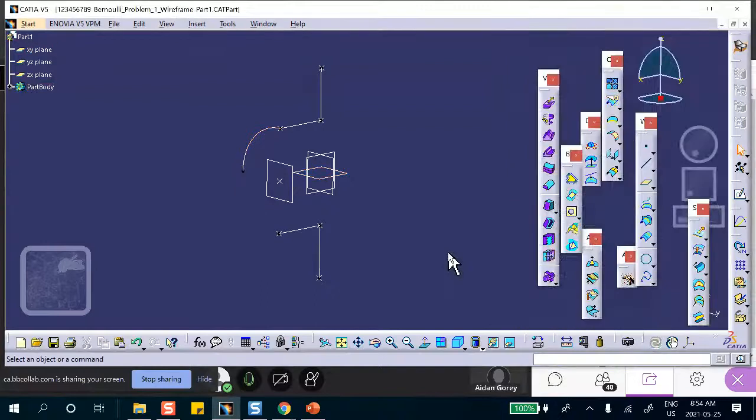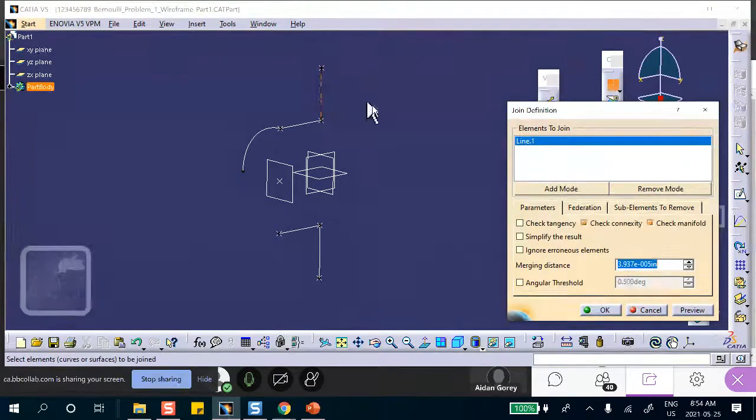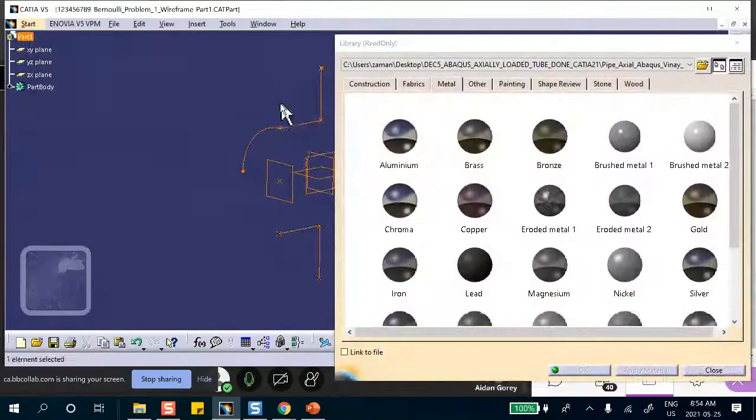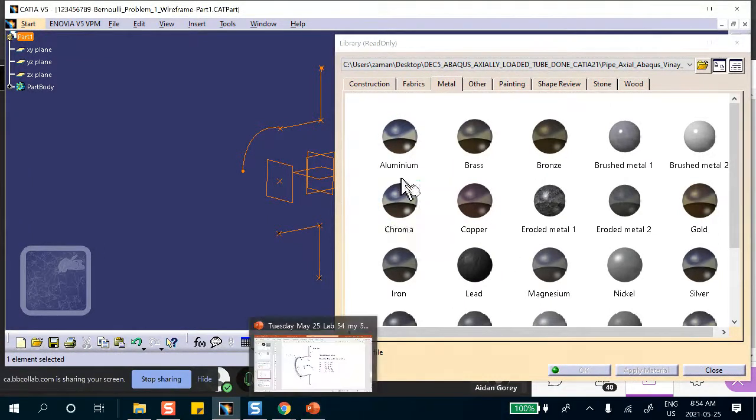And we say, okay. Now, these other guys, I can just either delete or later on when I do the meshing, just don't mesh it. As simple as that. I'm not going to delete it. I'll keep it here. How about that? If it's bothering you, you can delete it. Okay. Join this guy, that guy, and that guy. And we say, okay. And apply material on the part. That will include, of course, the join. I don't know, what did I have? I'll make it steel.